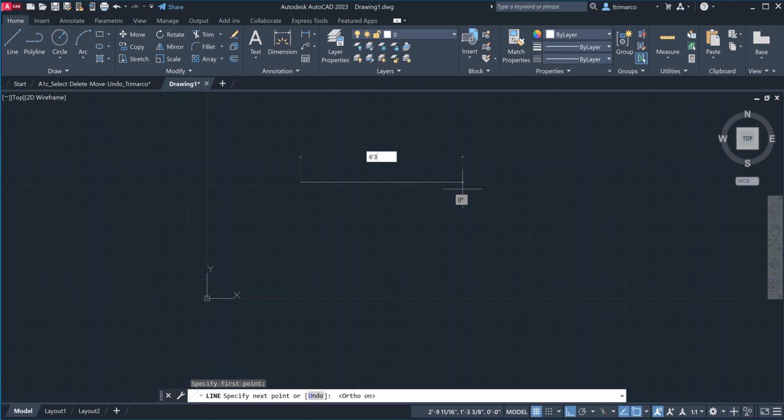The symbol for feet is the hyphen. Notice I am not formally typing this out like this. This is how we would write it, right? You don't need to do that in any digital program that you draw in, just the feet and then inches. You don't even need the inches tick, because if you're calling out the feet, AutoCAD is intelligent enough to understand that information, and it knows I want a line drawn 6 foot 3 inches from here.